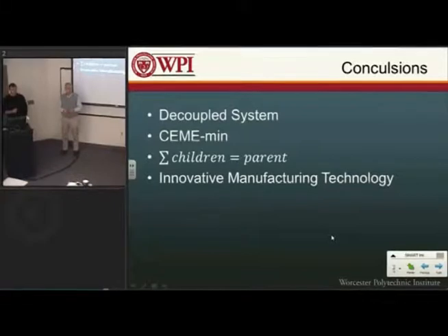I can see the potential. I worked for a medical device company over the summer. Sure. Stainless steel, small tubes. Sure. And I ran multiple tests on it, and what would happen is if the tube was too thick, it would clog in on itself against the laser, and it wouldn't actually have the material. Right. So the mandrel would allow you to actually get rid of the material that you're trying to cut. Right. So why wouldn't you, instead of using a mandrel, use high pressure gas or liquid, basically support the tube as you cut? Yeah. Certainly, it would be something we'd have to take into consideration during that iteration.